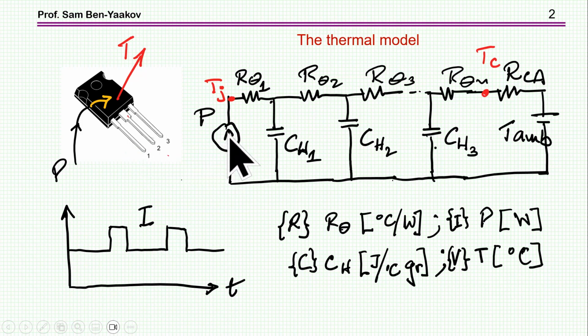So this will represent the power dissipated within the unit. These are the thermal resistances. The junction temperature is represented by the voltage here. The case temperature is the voltage here, and this is the thermal resistance between junction and case. Also, I'm showing here the thermal resistance between the case and ambient, and then we have the ambient temperature represented by, clamped by, a voltage source.